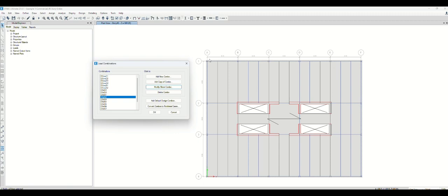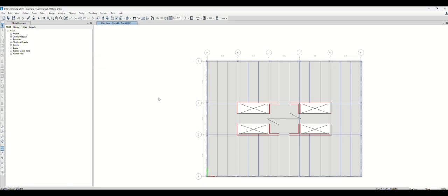For the column, which currently is composite beam only, the gravity frame column is meant to take only gravity forces, which is axial, not lateral. None of the columns and beams are contributing to the lateral system because we have all the beams moment released, right? So we most likely use the S1 and S2 load combinations for our column design.